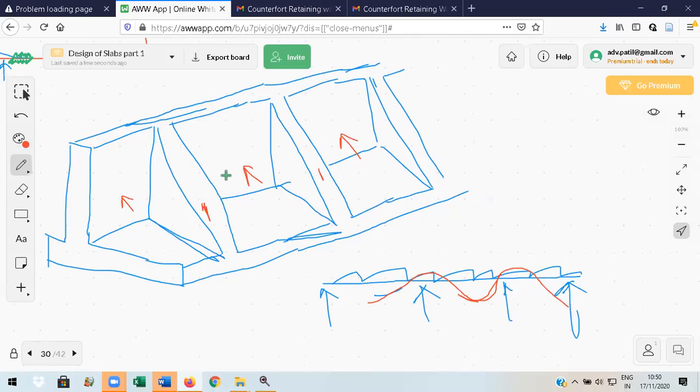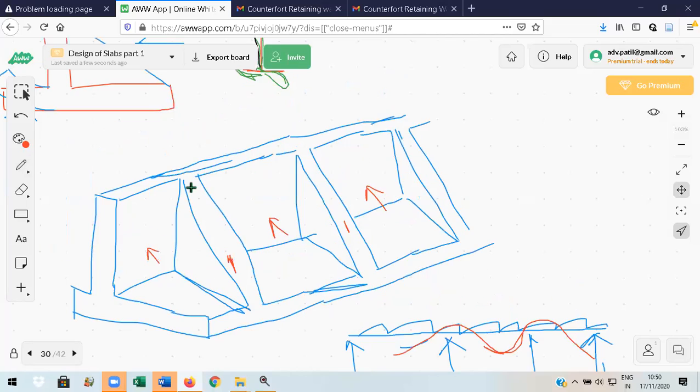These two are trying to hold this one, whereas the earth is acting pressure on this slab, whereas these two counterforts are trying to prevent it. They're trying to prevent this moving away. Because of this earth pressure, it tries to move away. The stem tries to move away, but these two are trying to hold the stem slab in position. Now, this is the earth pressure.